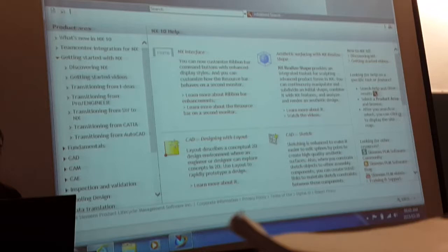So loads and constraints. Right, so what NX does is it works in a minimum of 3-step process. But there's an optional fourth step that you can choose if you want to. And that fourth step fits in just after the generation of the part, and it's basically the generation of what NX calls an idealized part.